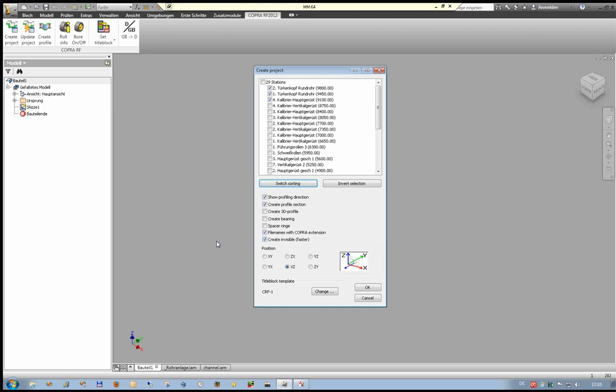That's a little bit faster because if you set this flag, Inventor doesn't show you what it's doing during the creation of the project. If you don't set the invisible flag, then each role that gets created is also showing up in Inventor.